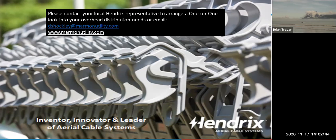I've seen them in Asia. I would imagine that they're still using the thin wall construction standards that they had for low voltage. If we were going to give the green light, we would have to see the type tests, and that those type tests were on IPCs connected to ICEA standard conductor that had the proper insulation walls. I mean, you can't take an IPC for an 80 mil wall and plug it into a 150 mil wall and expect it to work. You're going to have a heck of an arc and a hot spot.